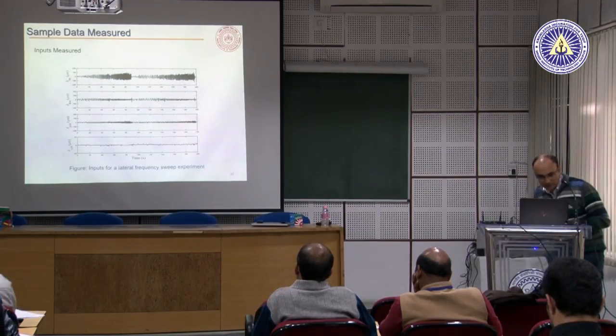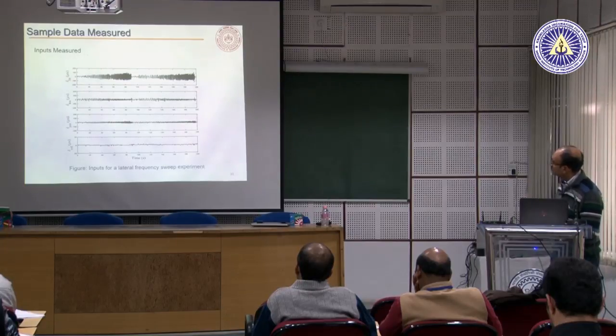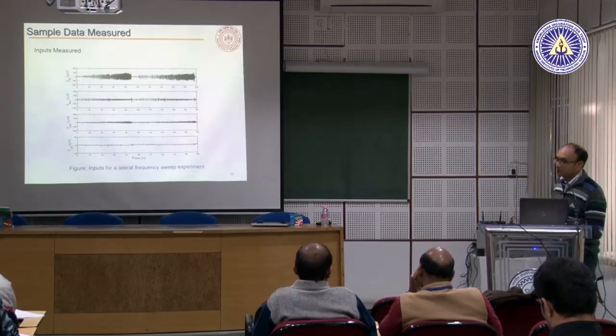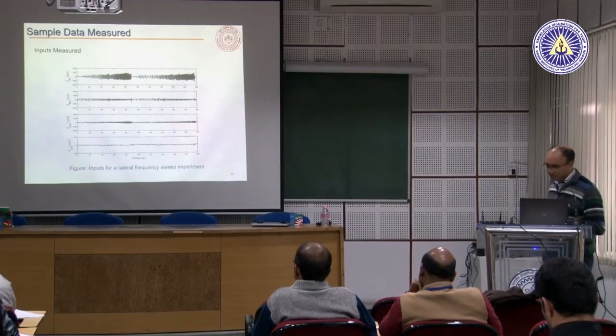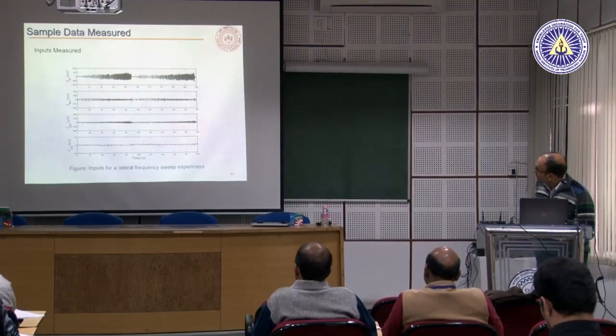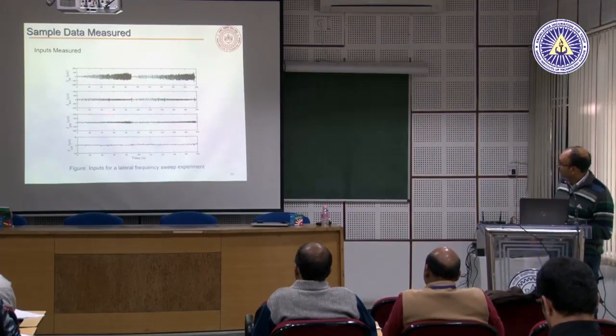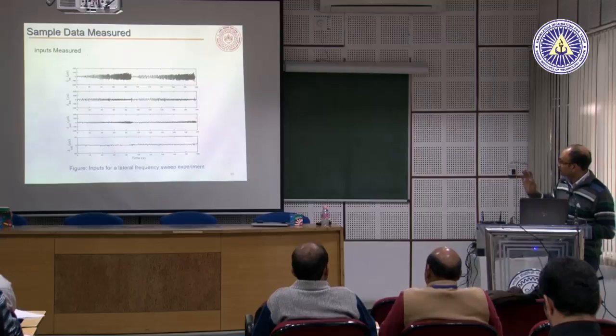This first one is actually lateral cyclic. So it gives in batches, and you increase the frequency. See here you can see the frequency is very fast. So you start with very low frequency, start increasing it slowly, and the same kind of thing is over here. Then this is longitudinal. Lateral is actually fine, but longitudinal, what happens? If you start giving big inputs, it starts oscillating very fast.